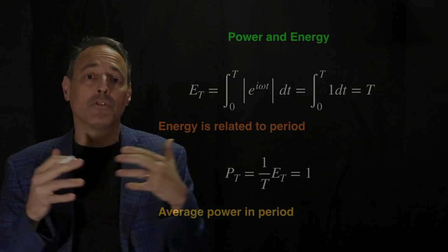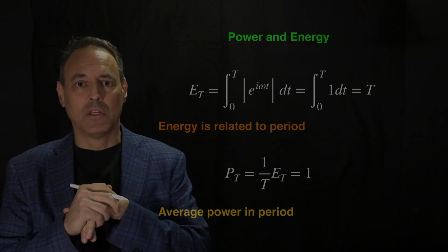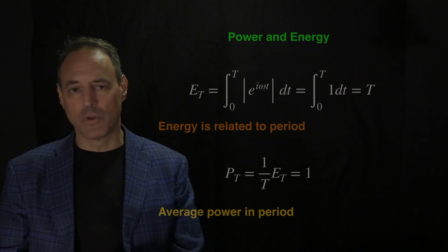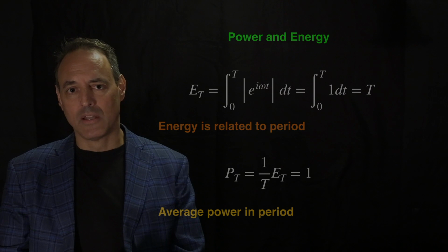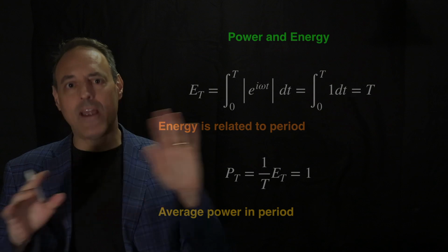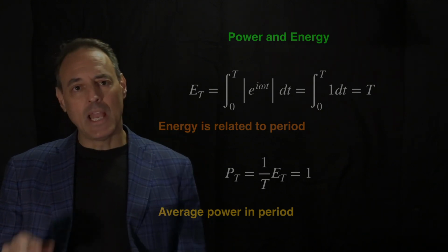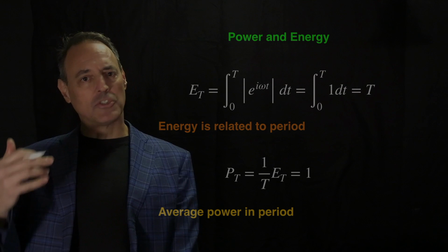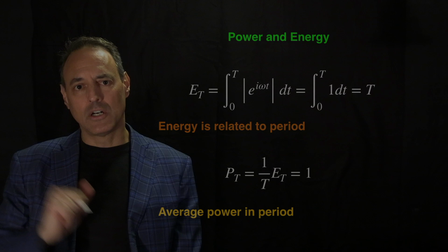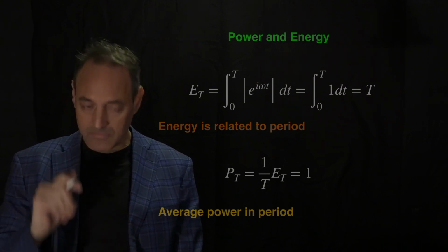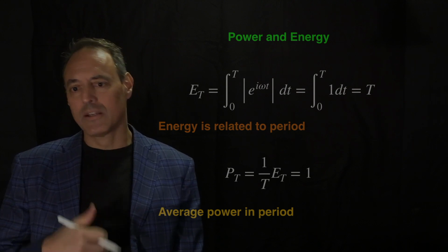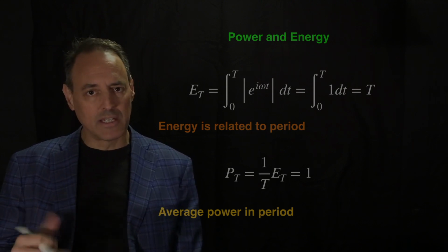And it's probably the most important transform that's ever been developed in human history at this point, right? It's taking a signal. This representation is one of the most widely used representations that we have, a canonical transform that applies almost across every discipline in the sciences. And really, at the end of the day, the Fourier transform is simply saying, if I have a signal, I want to represent it in terms of frequency content and the energy at each frequency. So it's a really nice representation that's very generic and easily used across disciplines. Very nice interpretable results.